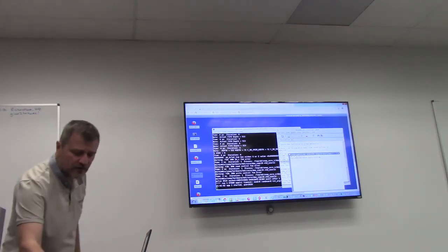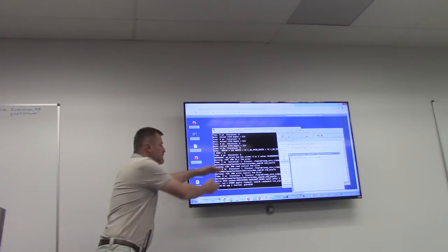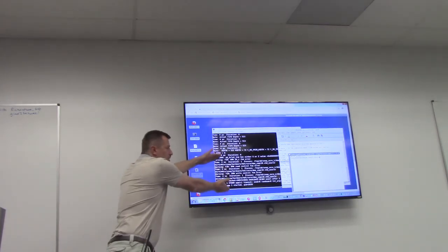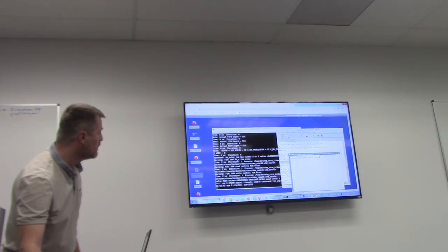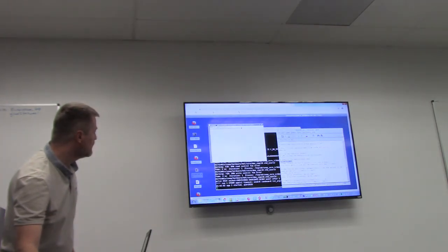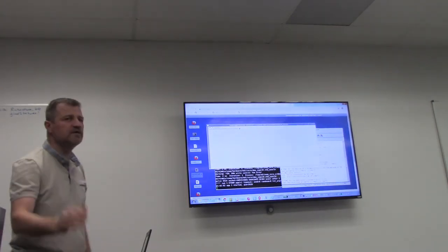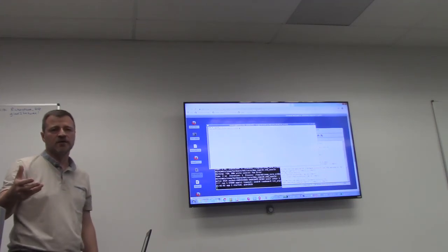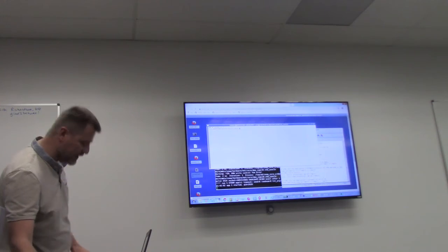So I'm in a new terminal. We could have that here, but it mixes up the simulation results and what you want. So for an experience, it's better to have a new window. It could be a simple terminal. The bad thing about that is that you need X11 to run. So if you are in SSH, you need to be SSH with X11 emulator, okay, or being on Linux.